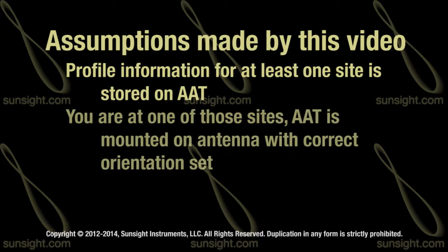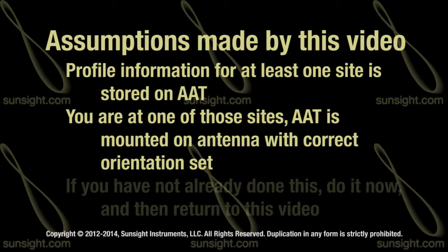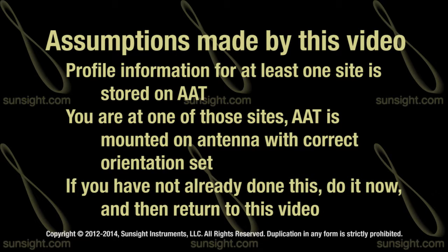and that you are at one of those sites with the AAT mounted on the antenna, an azimuth solution locked in, and the correct orientation set on the AAT. If you have not created profiles or mounted the AAT and set the orientation in preparation for capture, go ahead and do that now and then return to this video to continue.